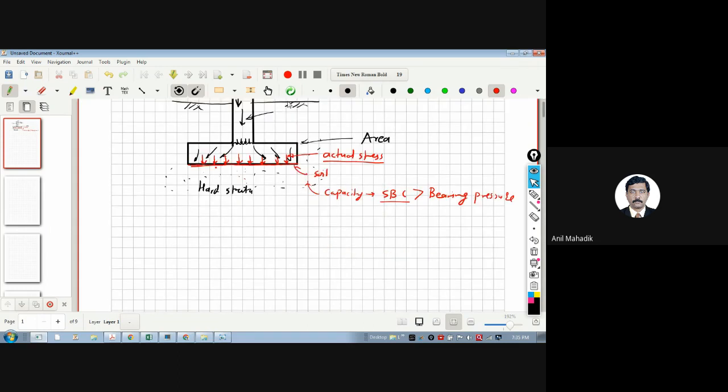Okay, first. Due to this above load, what will happen? There is punching, shear. This downward load is there, so this is the action, the downward load. Due to that action, there will be a reaction offered by the soil. The soil will offer reaction to that, and this we call upward pressure. Then there will be equilibrium, downward force and upward reaction. That is the equilibrium condition. So we can say that it is upward pressure due to soil.